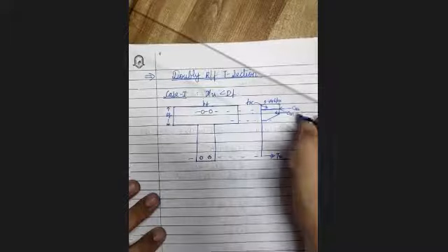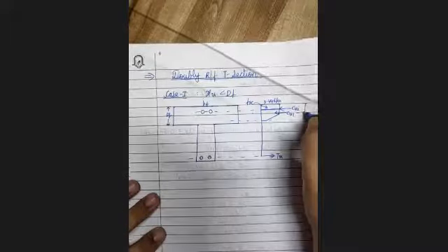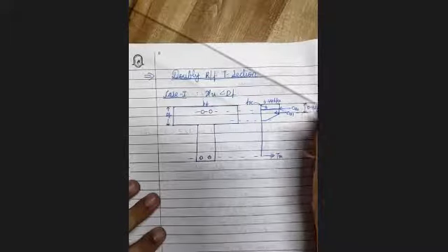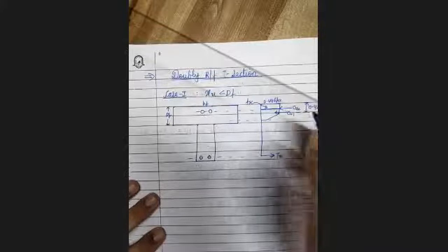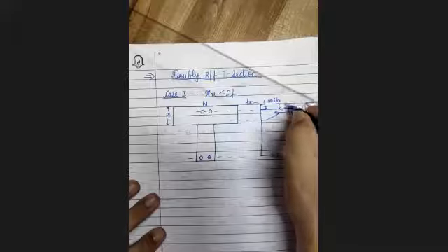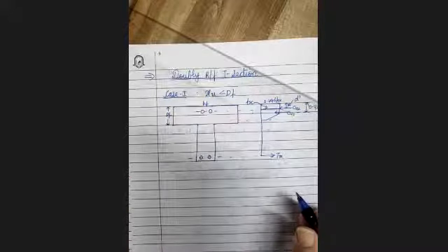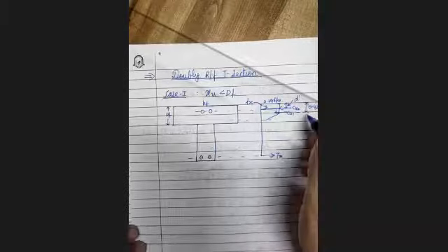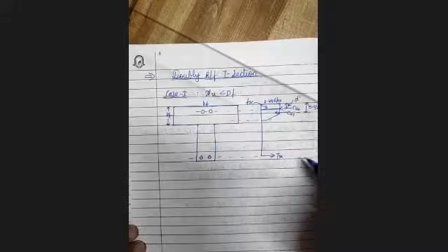This CU1, we already know, is at a distance of 0.42 XU, and this distance is B dash, let us say. From this you can calculate the lever arm. This is D minus 0.42 XU and this is D minus D dash.